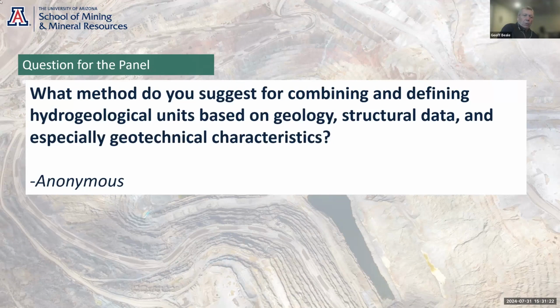If you see water levels that are different, it's telling you you haven't got very much flow between those holes. So the first thing to look at is water levels, then add the structural models. And if you can correlate jumps or differences in water level with the structures, then you're getting into having a good definition of the hydrogeological model and the flow system. And I always do that way before I look at any permeability numbers.